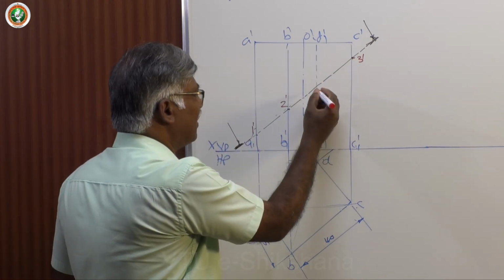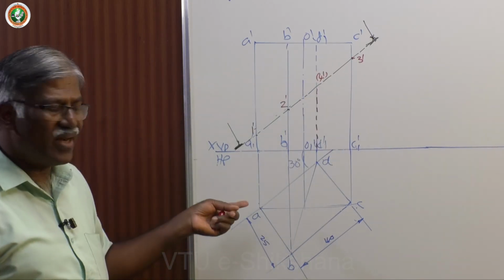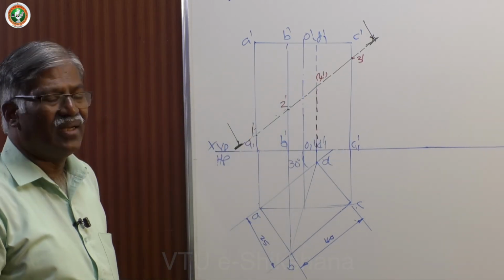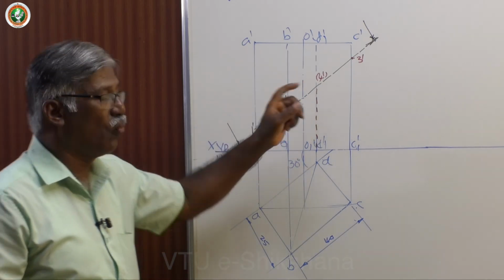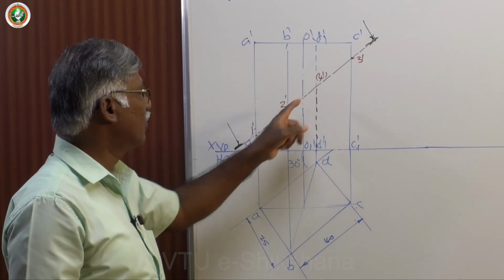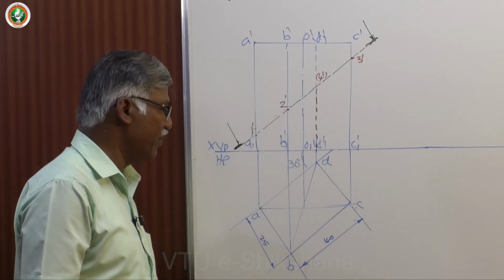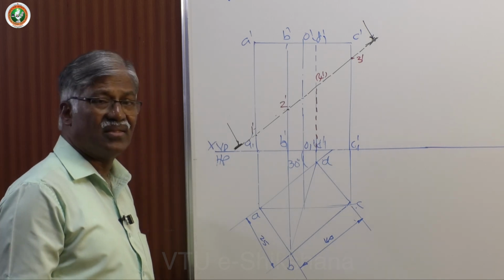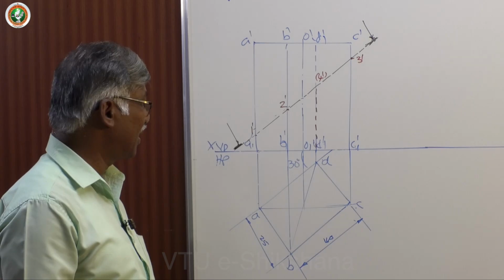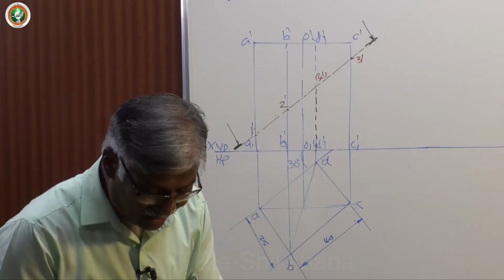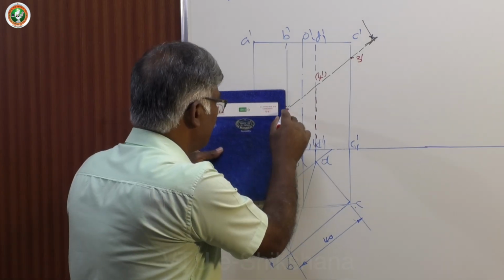Now, after naming visible edges and intersection points, you name the invisible edge in bracket. Any more points? No. Only 4 lateral edges, all lateral edges intersecting with the section plane give you 4 intersecting points, 1 dash, 2 dash, 3 dash, 4 dash. So that actually coincides with corners only. You need not name it unless the situation demands. If you need that particular top view details, then only you project it, otherwise no. Now dark all the remaining portion of the solid.